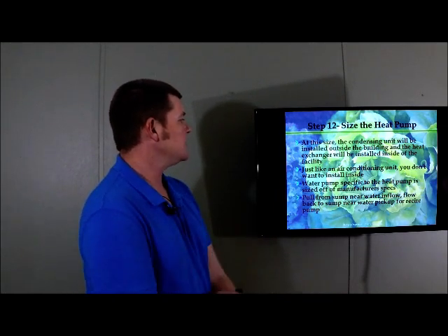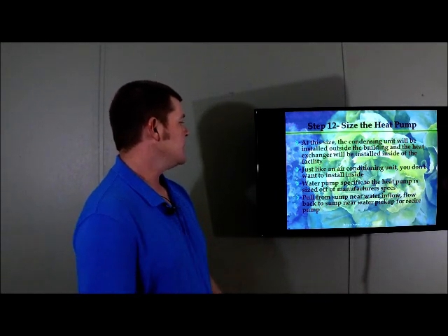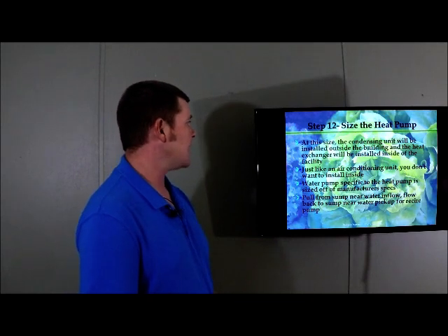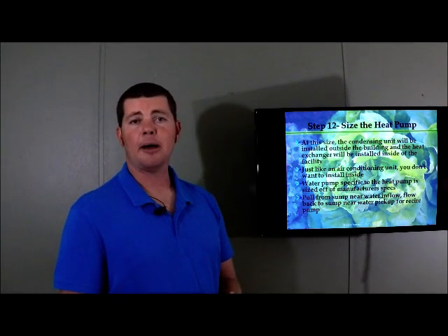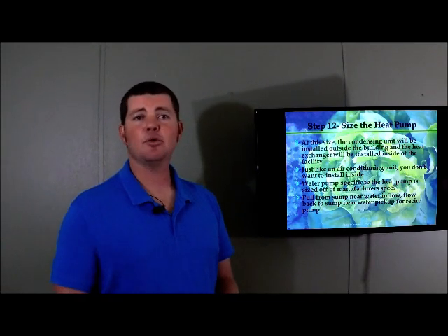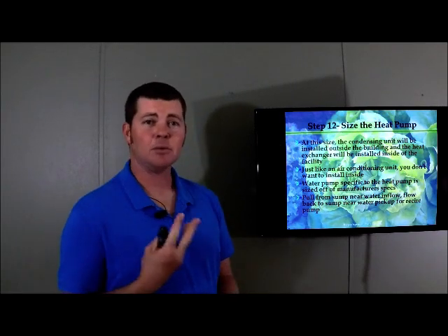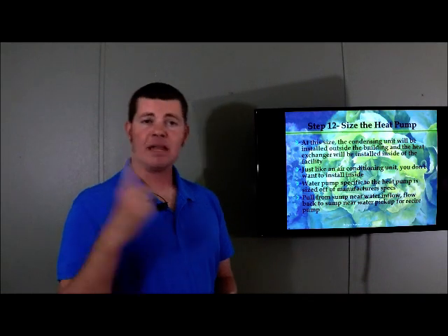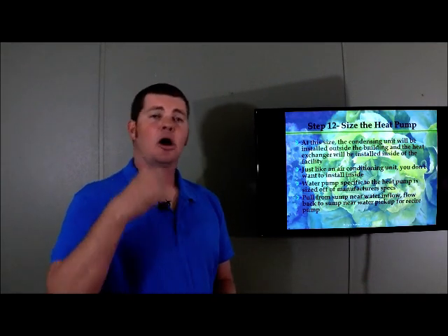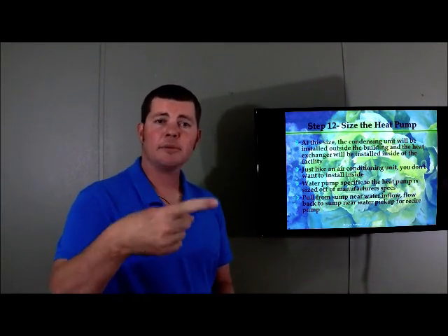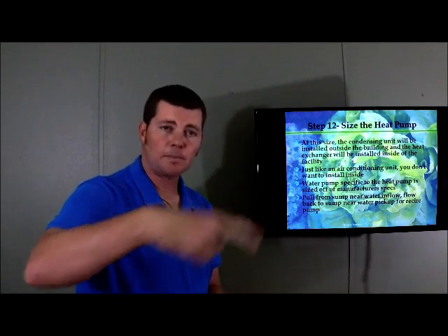Water pump will be specific to the heat pump, sized off of manufacturer specs. So the heat pump has its own water pump. It doesn't have to do with the other 2 water pumps that we're already using in this design. So it's got 3 water pumps in this design: the main recirculating water pump, our water pump for the oxygen requirements, and our water pump for the heat pump requirements.